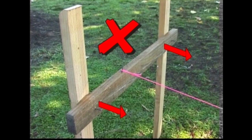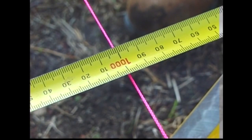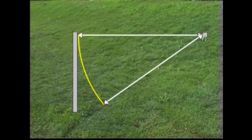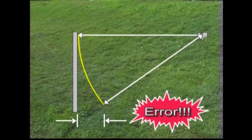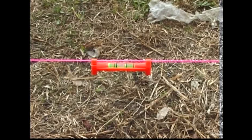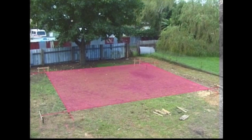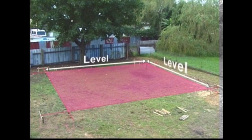Accuracy is extremely important in setting out. Accurate set-out measurement can only be achieved on the level and not on an incline. This means all string lines, and therefore all profile edges, must lie on the same level or horizontal plane as setting out proceeds.